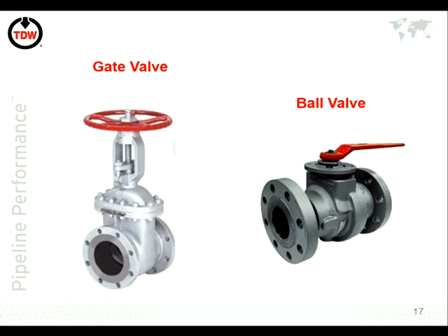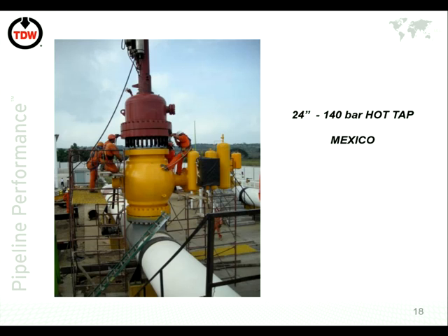So this is a 24-inch hot tap which occurred in Mexico, and as you can see, the fitting has been put on the pipeline as we showed before, and this is not a sandwich valve, this is a full operational ball valve. The reason that's there like that is after the tap has been done, that valve will be an integral part of the pipeline, and it will remain there. That is not our property, it is the pipeline operator's property.